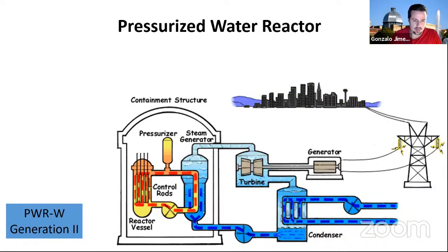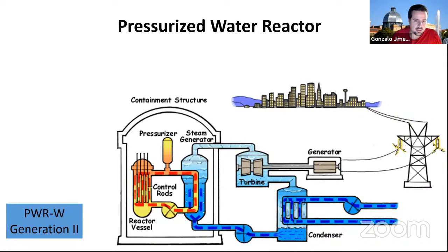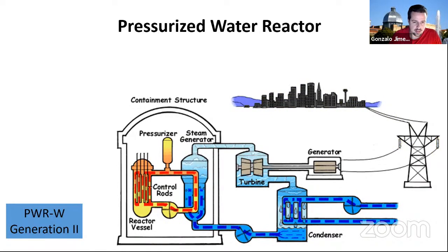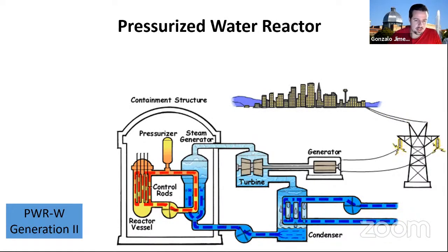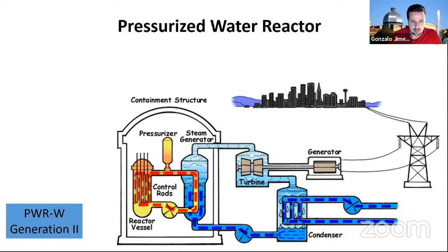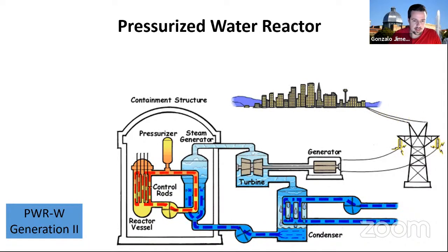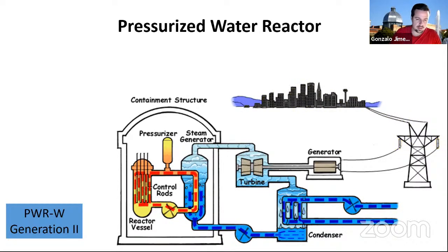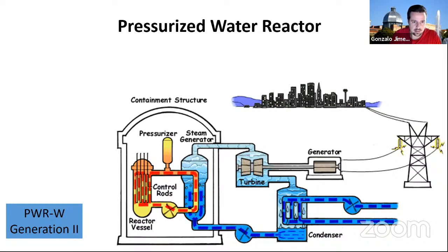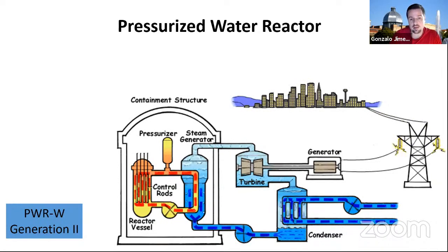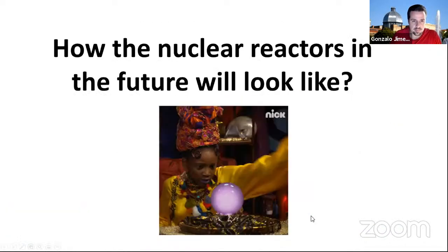Even as I told you, you have stopped the nuclear fission, you are just experiencing the residual heat. So when we're talking about safety systems, the primary focus is on the cooling, because of the consequence of having this high residual heat in the core, even if we don't have nuclear fission. So that's something that you have to know.